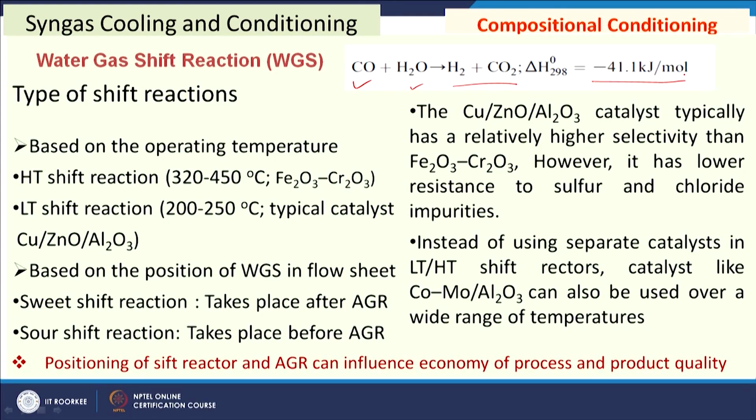So, if this water gas shift reaction takes place before the acid gas removal, then it is called sour water gas shift reaction, and if it is placed after the acid gas removal, then it is called sweet water gas shift reaction. So, we have two types of reactions, sweet shift reactions and sour shift reactions.